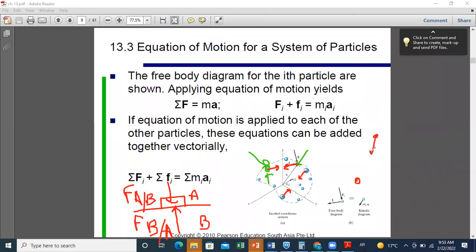So here, for example, in this case, you have mutual attraction between the particles, and the forces are opposing each other. So now when you do the summation of all forces acting on your particles, the red forces, which are attractive forces between your particles, will cancel out. We call them internal forces to the system. So you will only be left with the forces in green, which are external forces on the particles.